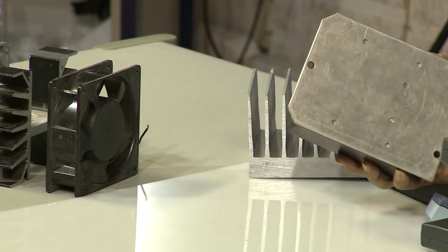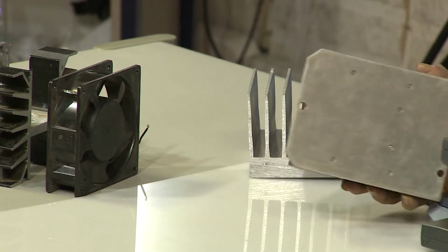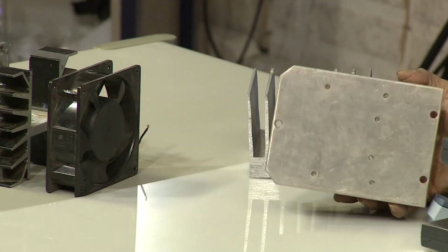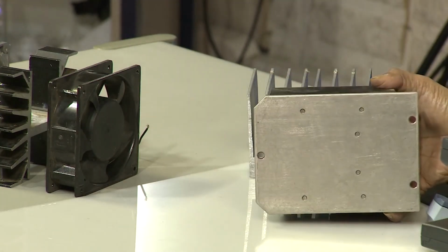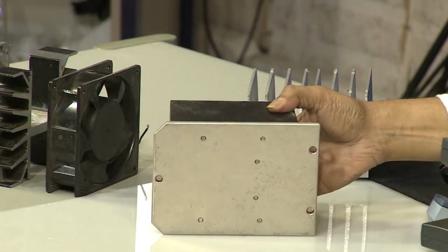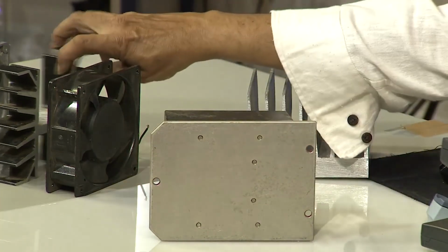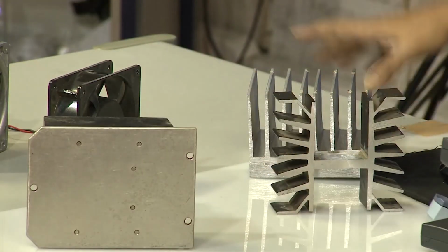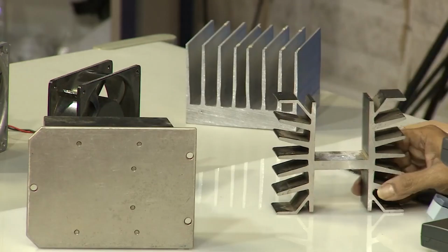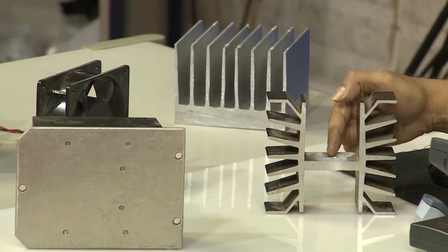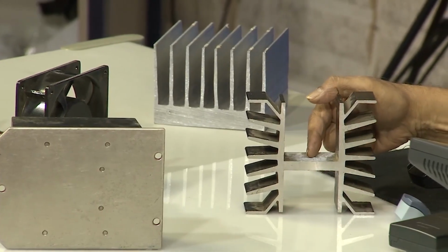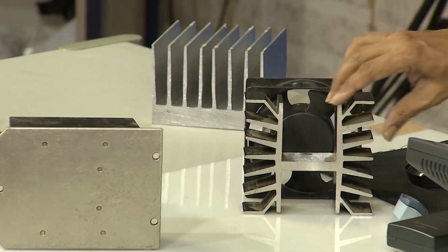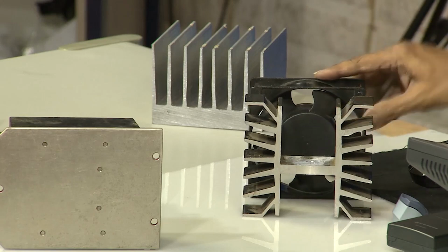And then here comes the thing, what do we do about this surface? Do we keep it as it is, or how do we cool it, or whatever it is? This is where our two levels of analysis are required. One of them is, if you see, this heat sink has been made for fan cooling of devices which are mounted on this surface. And then we also have a fan here which, as I have told you earlier, approximately covers these areas.